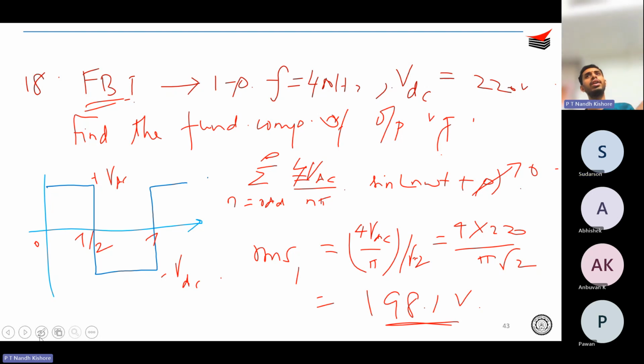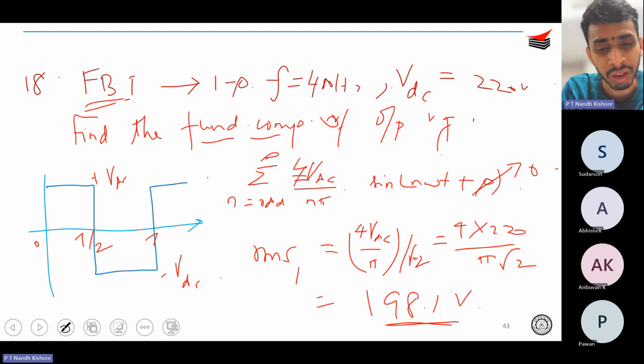Yeah. So the point is, for example, if you take half bridge, you understand, right? You don't make full utilization. In a half bridge inverter, you only get plus VDC by 2 to minus VDC by 2. That is one thing. Second thing is, even in a full bridge inverter, for example, you say that the output power is supposed to be V naught into I naught. But the useful power is actually only the fundamental component. Rest of them is harmonics, which will just cause heat up, right? You don't want that. Correct?